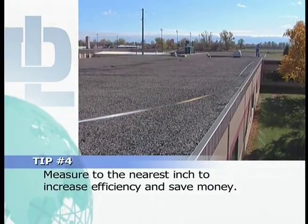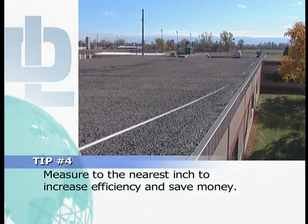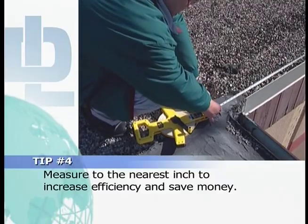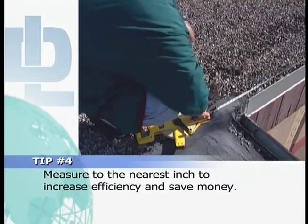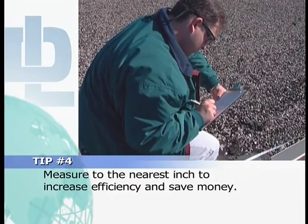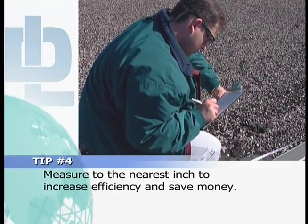As you measure the roof area, write all measurements to the nearest inch. Accurate dimensions only increase efficiency. A little extra effort up top makes the difference between saving or losing time in the long run, and it ensures that you don't take the chance of missing a needed dimension.